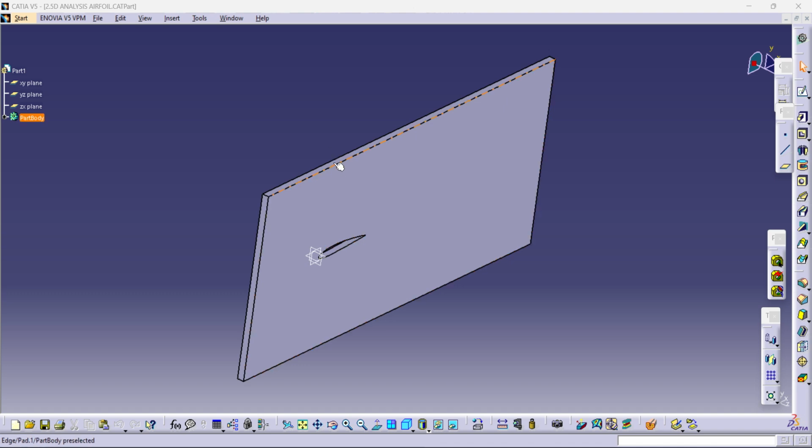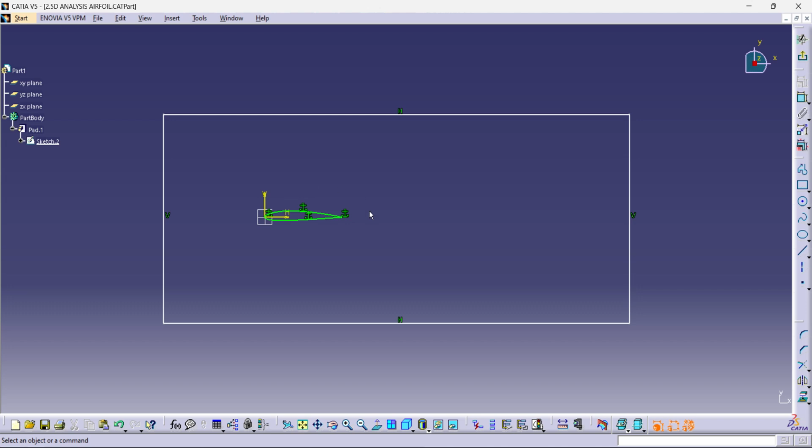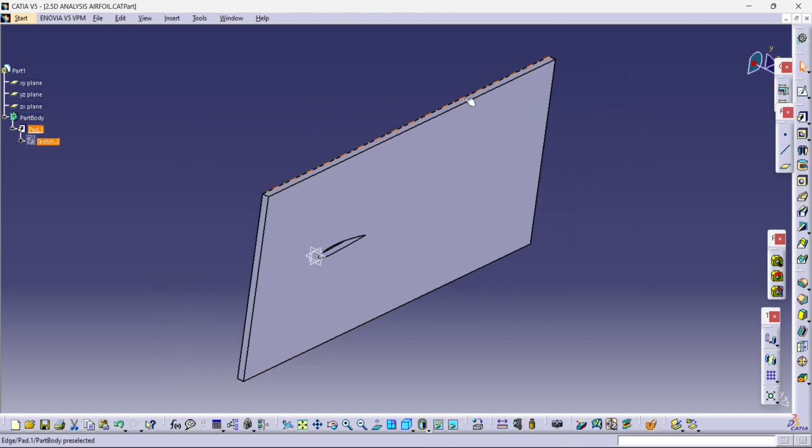So I'm taking a thin slab kind of model, with a thickness of just 10 mm that I have given here. I have used the NACA 412 airfoil. I imported the airfoil using an Excel sheet with the coordinate points, then increased the scale to 100 mm, then created a domain around it, and then padded it. I did the mirror extension on both sides by 5 mm, so totally 10 mm thickness. This model only I'm going to use for the flow simulation using Ansys Discovery.